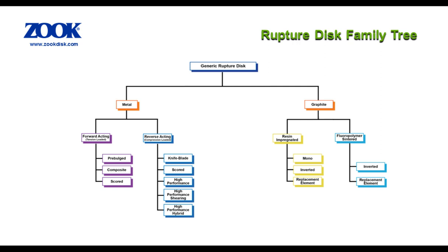Again, there are several variations of reverse-acting designs available that are tweaked to offer increased available burst pressure range, tighter burst control, or for compressible or incompressible service. It should be noted that compression loading of the disk allows the highest cycle life at operating pressures up to 95% of the marked burst pressure without increasing fatigue or nuisance bursts.